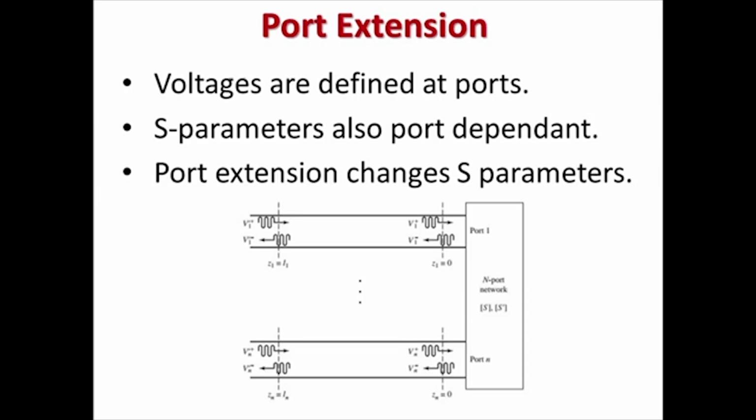Similar thing here. Now, one thing that we have seen in the first lecture today is that in general, at microwave frequency with waveguide type of things, we cannot define voltage uniquely, but under certain restrictions we have defined it. But that definition, we said at that time, is only at a particular terminal plane, at a particular port, where I can define uniquely a voltage or current.